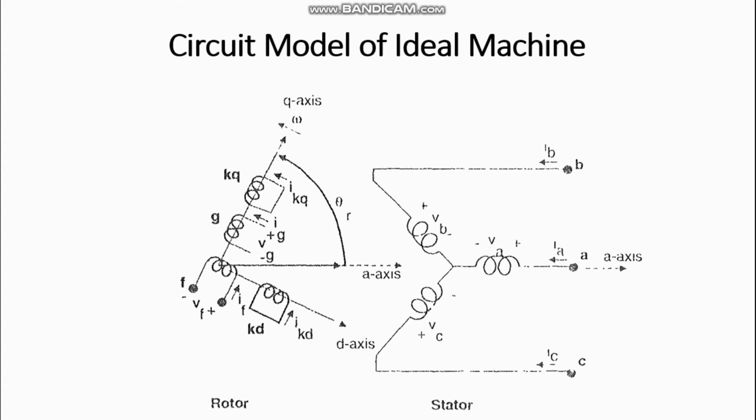As we know, a synchronous machine operates on the principle of magnetic interlocking. So if your supply frequency is, suppose, 50 Hz, and it is a 4 pole, 50 Hz structure, you are going to get a 1500 rpm rotating stator mmf.